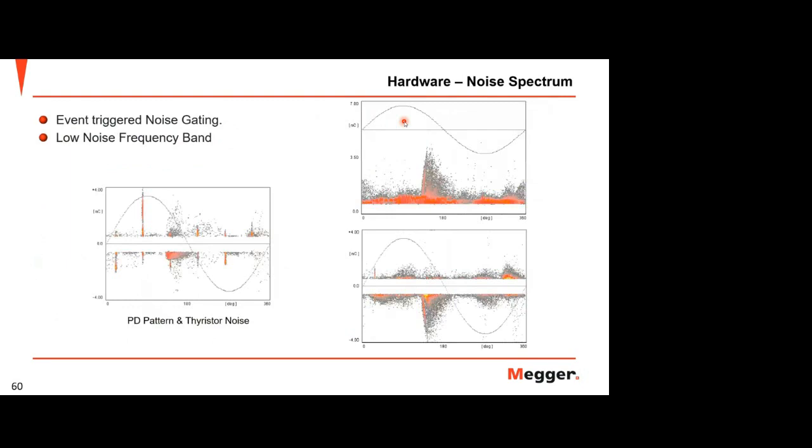So sometimes we use spectrum analysis to reduce some noise, like thyristor noise in some generator. You can identify it from this signal. Mostly every 60 degrees, you can see some noise. So if you select this, it means there is some thyristor noise on your system. With spectrum analysis, you can reduce this, you can avoid this noise, something like this.